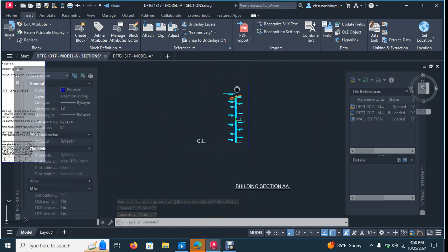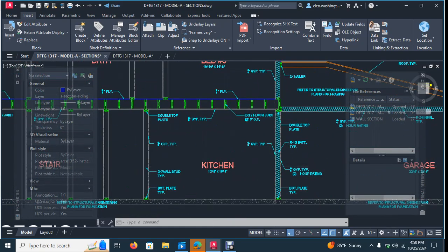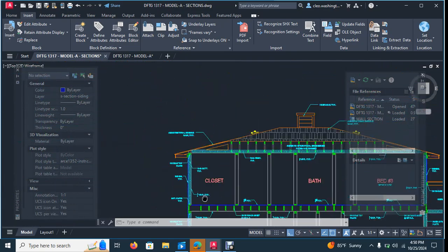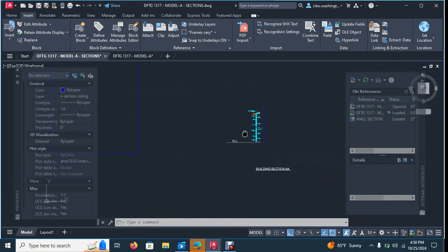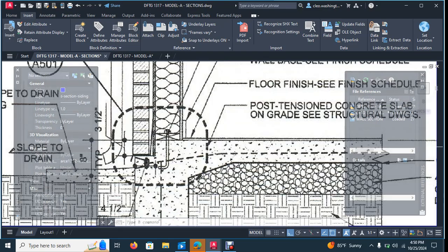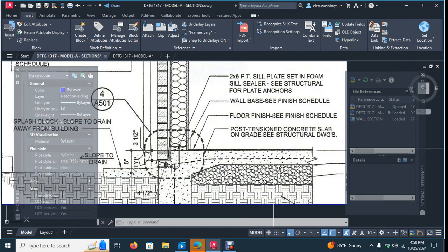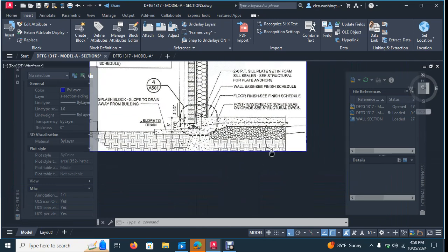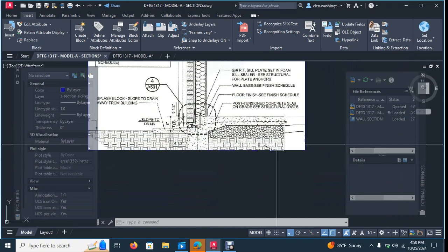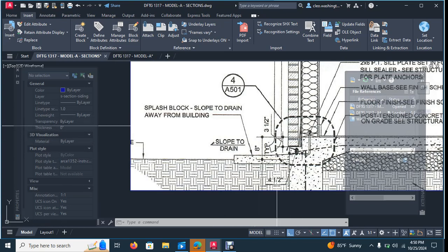So we'll have two wall sections. We'll have this one, and then we will have another one that's actually going to cut through the brick. We'll draw that one second, but right now we're gonna go ahead and hatch this one out, okay? So first things first, we have to get the foundation right. With the foundation, we're gonna show the anchor bolt. We're actually gonna show the grade beams. We're gonna show the compacted earth and the compacted fill, and we're actually gonna show the grade on this side as well. We're gonna call things out as we go, all right?